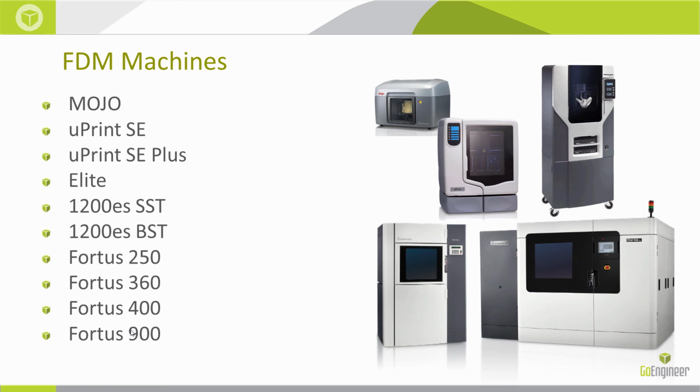PPSF and Ultem start at the Fortis 400 level because it's outfitted for the higher temperature materials. Those two machines come with two build envelope options, a 10 by 14 by 14 small envelope option and a 16 by 14 by 16 large envelope option. Those are the machines pictured in the bottom left-hand corner. And then the big boy, the flagship Fortis machine, the Fortis 900, is pictured there in the bottom right. This thing's a beast. It prints everything, and it has a build envelope of 36, 24, 36.